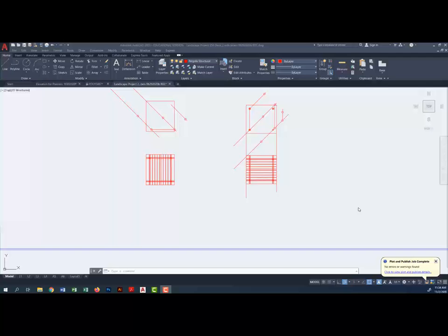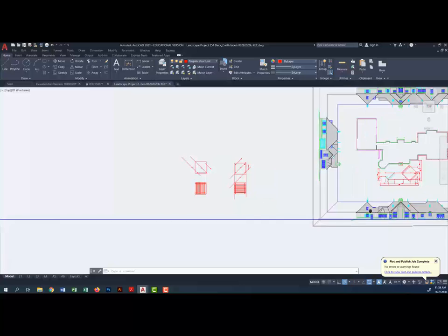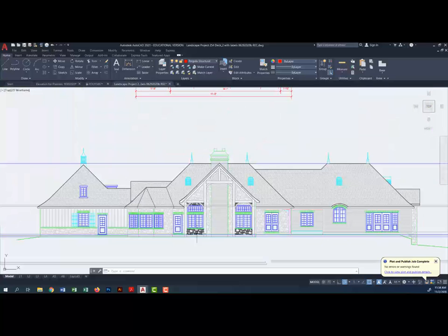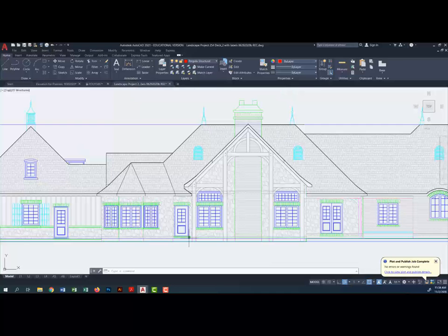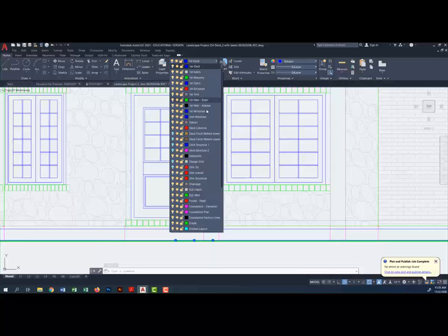Now, in order to create the elevations, I need to refer back to my sketch to determine heights. How tall is this pergola going to be? So first of all, I'm going to move to my actual drawing of the house elevation to determine the heights of the deck. And what typically you do is this first step from a house to the top of the deck should be 6 inches. It's mandatory by code. So this is my blue deck, and the step between deck heights, I'm going to make 7.25. So this line here actually represents my second deck, or my lower deck.